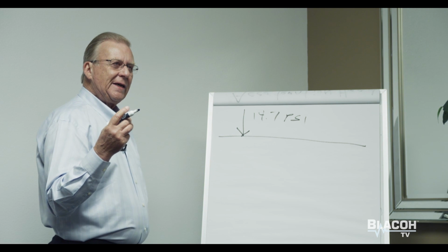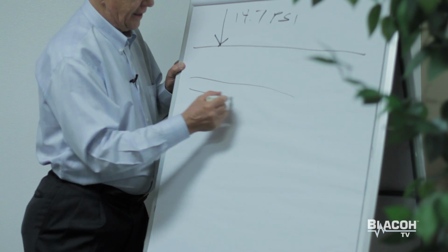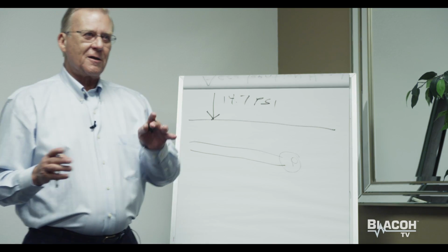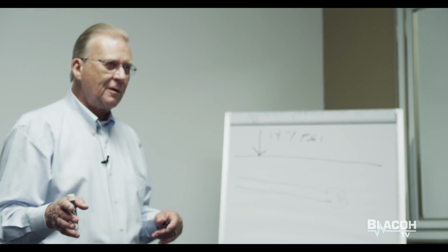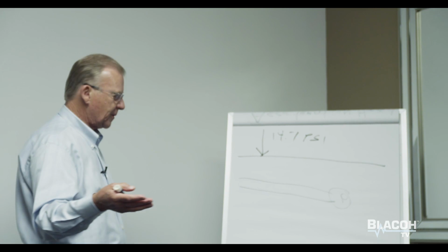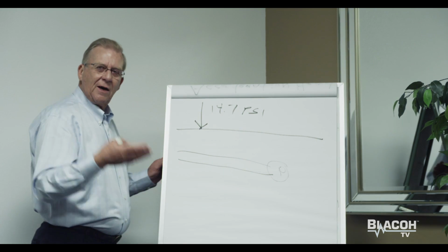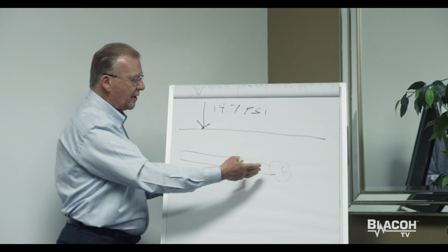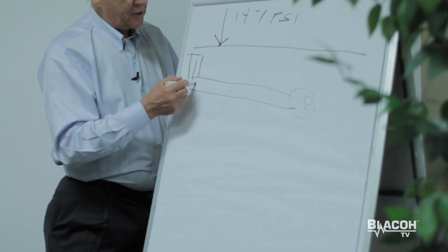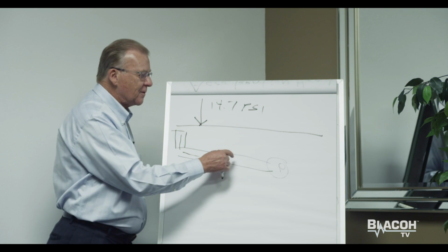Now, what's important about that is that if we end up with a relatively long inlet system before our pump, we don't have to go back to that friction loss chart. Remember, we talked about steady state flow versus reciprocating or start-stop flow. Okay? So the pump is going to create a low pressure area, assuming that we don't have a lot of inlet pressure. Atmospheric pressure, whether it's a tank or whatever, is going to push the liquid into the pump. Okay? But it has to overcome this friction loss.